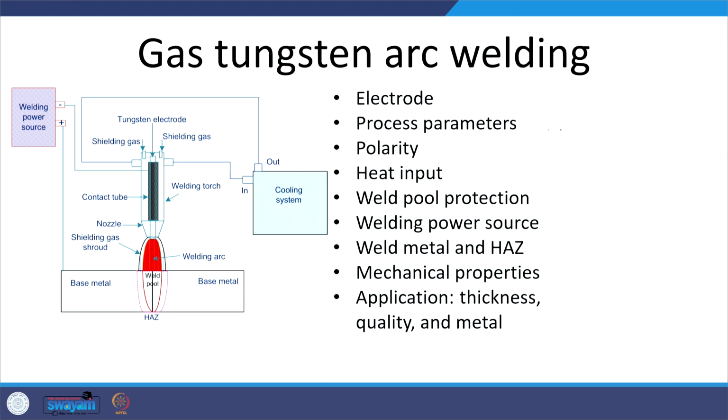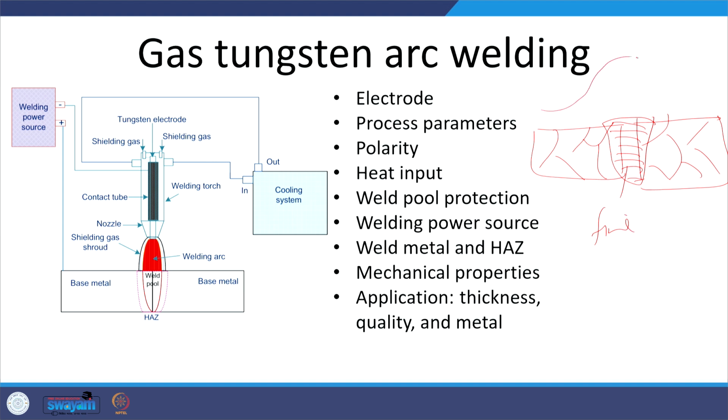For example, if the base metal has a very coarse grain, produced say by casting, and now the weld joint is to be made, since we have a very coarse grain structure in the base metal produced by casting, when this is welded, it will produce an extremely fine dendritic grain structure. This in turn can result in the weld's property variation in terms of hardness: the base metal is less, but the weld zone is very high. This is attributed to the fine grain structure that will be produced, and this is particularly true in the case of cast metals.